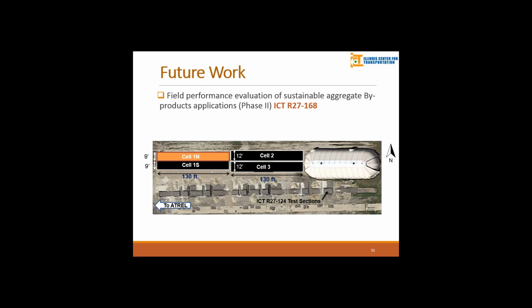So the future work of this will be the work of Isam. He will work on the ICT new report of 168. They're going to do field testing of these quarry byproducts. They have different cells with different combinations of QBs or large size aggregates or RAP or RAS, and they will test them under different loading conditions, for example, as a working platform, or base or sub-base. So we're going to see how they work in the field after the laboratory testing.